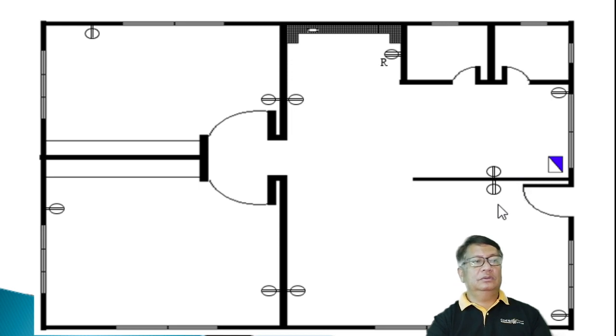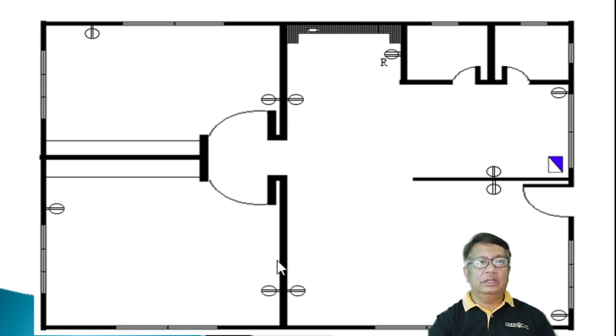Okay, so as you can see here, as much as possible, if there is a chance, then try to locate your convenience outlets back to back. For example, these two, no? Why do we do this, or why is it advised? So that it might affect the economy of our design, no? So more or less, siguro hindi masyadong marami yung wire na magagamit natin.